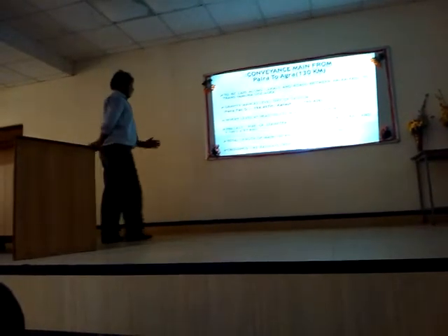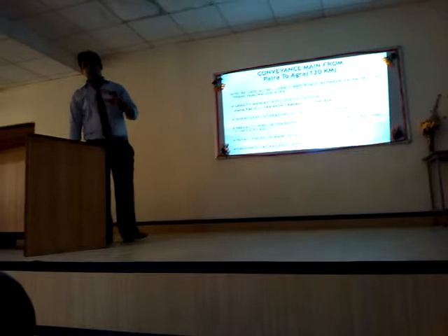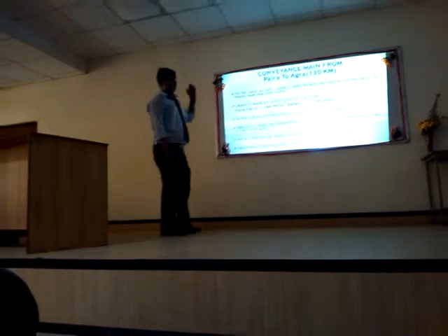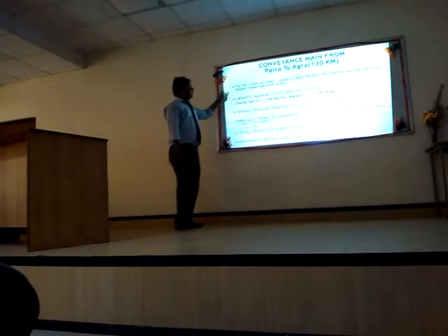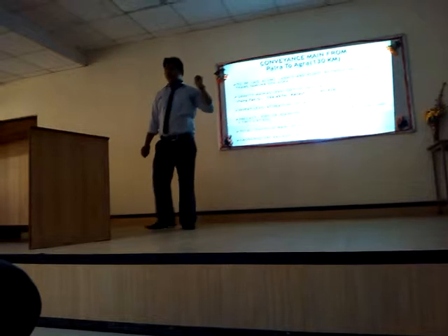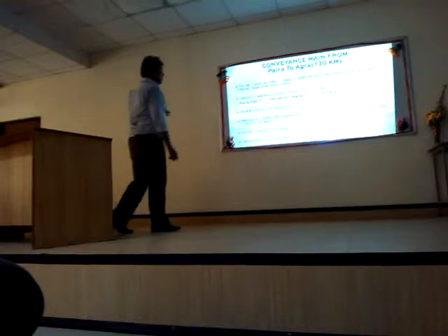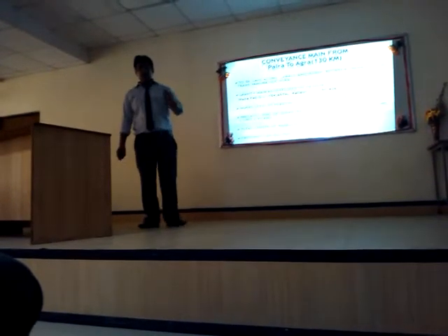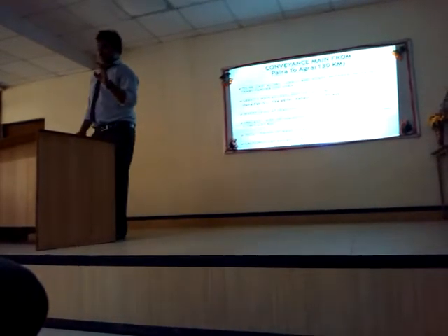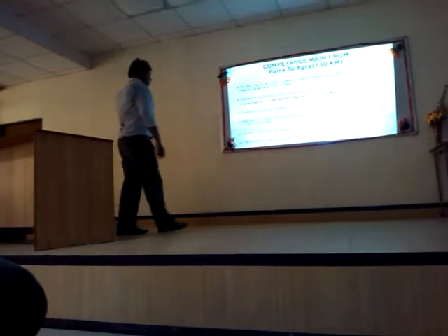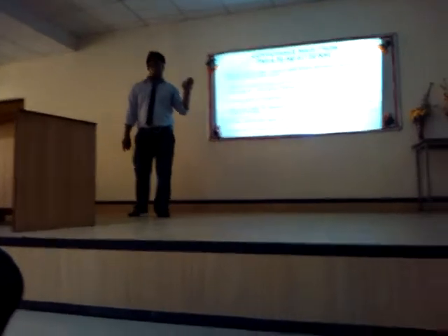Now, as I told you earlier, we use the Upper Ganga canal. We should take water from the Upper Ganga canal to Agra. So we regulate from Palra, which is approximately 130 kilometers away from Agra. We are required to lay an underground pipeline of approximately 2,500 mm diameter, which comes from there to Agra, to WW1 Sikandra.